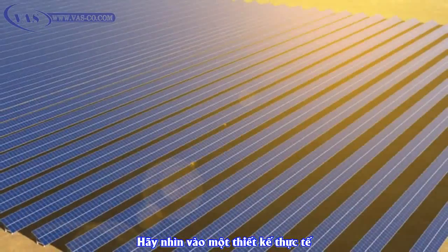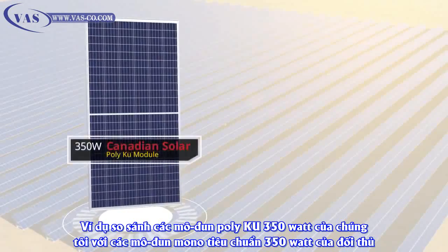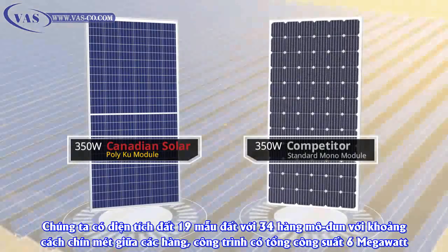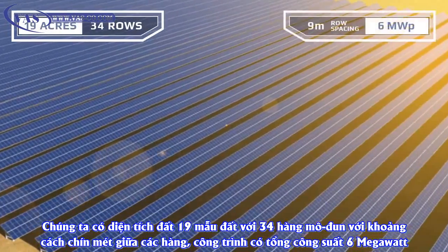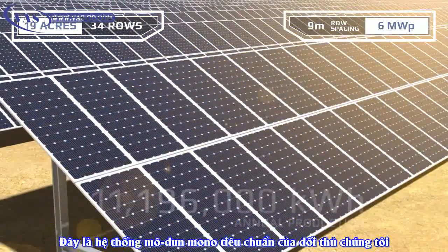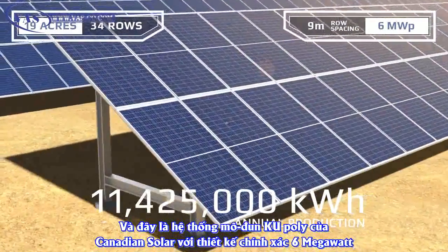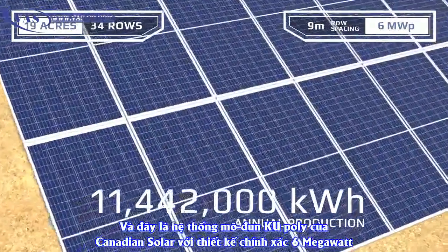Let's look at a real-life design example, comparing our 350-watt poly Ku modules to our competitors' 350-watt standard mono modules. We've got 19 acres of land, which fits 34 rows of modules, with 9-meter spacing between the rows for 6 megawatts total. Here's our competitor's standard mono system.